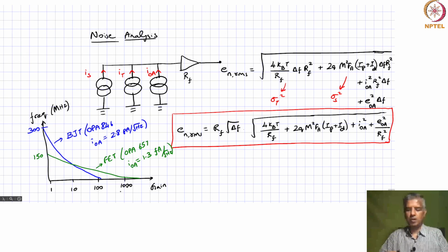So in a lot of these optical sensor applications, we try to get a FET type amplifier, especially at the front end, because that's very important. The op amp that you use for the TIA has got to be as low noise as possible, because any noise that's generated there is only going to be further degraded in the subsequent stages. So we'll have to be very careful about that.